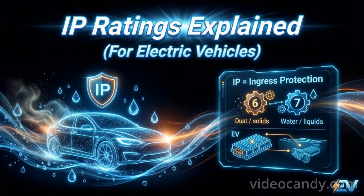Finally, battery packs often list IP ratings, like IP67 or IP69K. IP stands for ingress protection. The first digit tells us how well the battery is protected against dust, and the second digit indicates water protection. For example, IP67 means the battery is fully dustproof and can survive temporary immersion in water. These ratings help engineers quickly understand the safety, durability, and compatibility of battery packs.